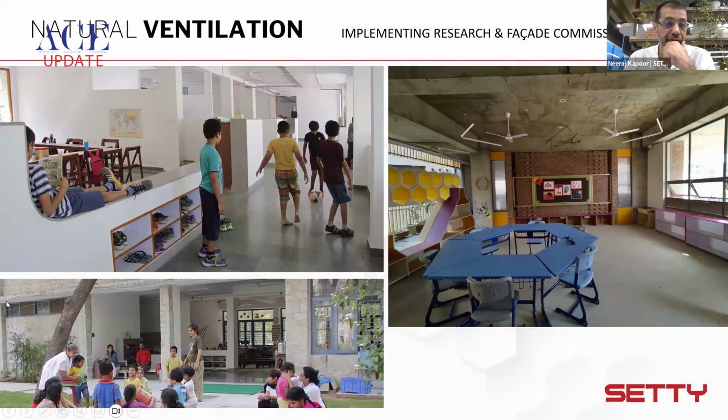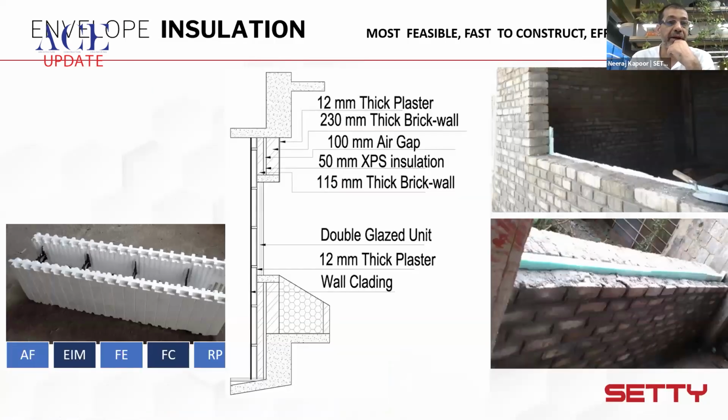it's a small school, but the kind of free natural ventilation that you feel here is quite extraordinary. On similar ground, there are many such schools which are coming up all over in different parts of the country. This is Prakriti School. Again, you'd see the operable windows there. This is also looking onto the corridor, a singly loaded corridor on the other side. So if the building is completely enclosed, then you need to start looking beyond thermal mass and natural ventilation. You will need insulation.